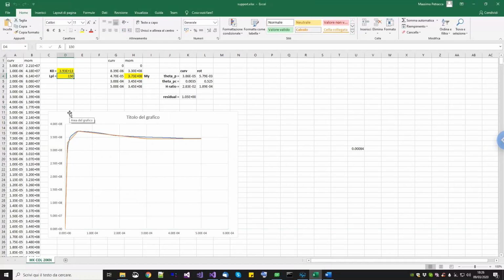When we choose the beam element with the Lobatto integration scheme, the bottom Gauss point has exactly this characteristic length because the weight of the Gauss point is 0.05 times the length of the beam, which is 3 meters, giving us this 150 millimeters.